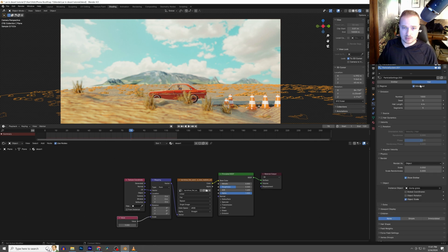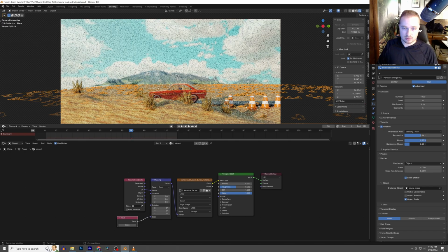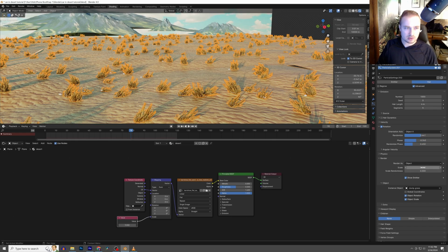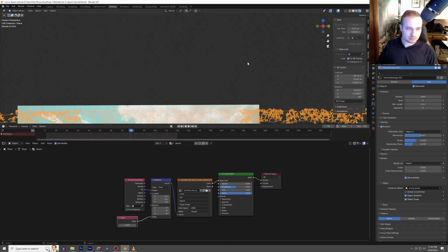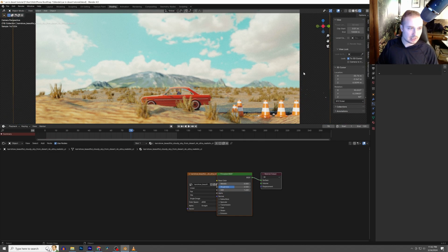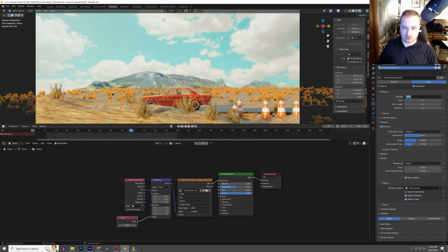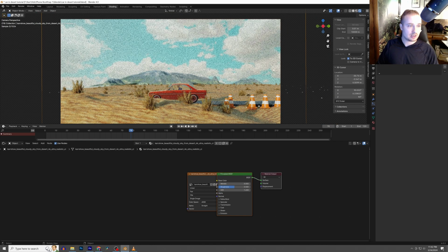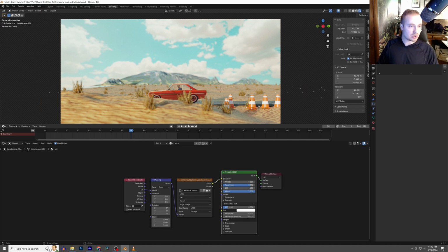We'll say advanced rotation, randomize. You can randomize the phase. If you add a little bit of phase, you can randomize the phase. Let's see, what did we do here? Object rotation. I think that's what we did. There we go. That looks better. And that's good. And again, there's too many of them. So we'll say 200. And that looks pretty good.